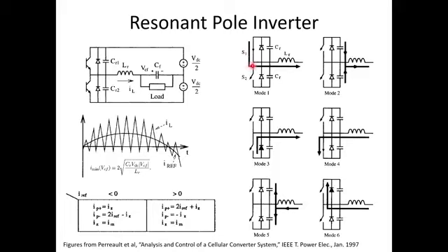Well, what I'm going to do is, for example, turn on the top switch S1. Suppose the top switch S1 is on. So long as VCF is smaller than VDC over 2, I've got a positive voltage across the inductor, and the inductor current is going to ramp up, right? So that's going to be some positive rising current here. When I get to some peak commanded current that I desire, this is a current controlled converter, I will turn off S1, okay, under zero voltage switching, because this capacitor is snubbing the switching transition, okay.